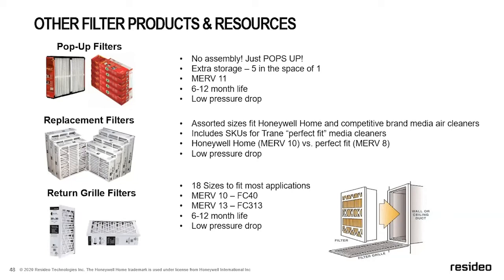We have replacement filters as well. So plenty of SKUs for Honeywell Home and competitive brand, as well as the Trane Perfect Fit media air cleaners. The Honeywell Home models are MERV 10 and the Perfect Fit are MERV 8. Again, low pressure drop. And then a newer portion of this portfolio is our return grill filters.